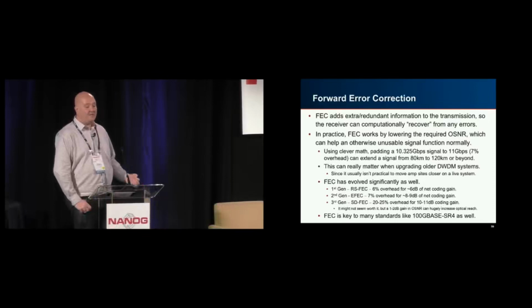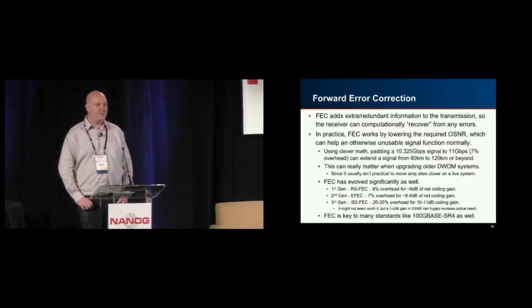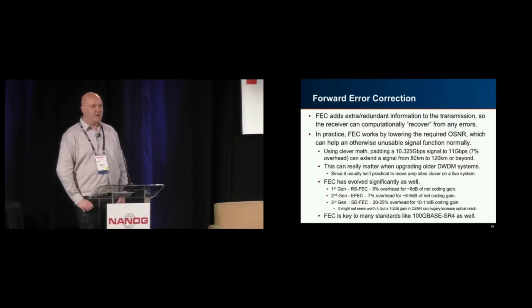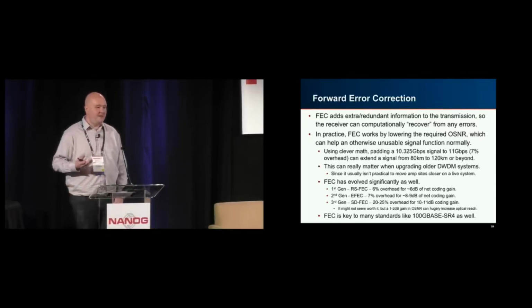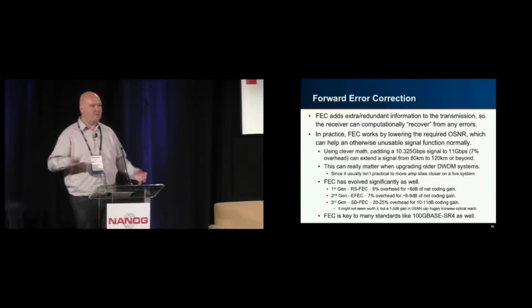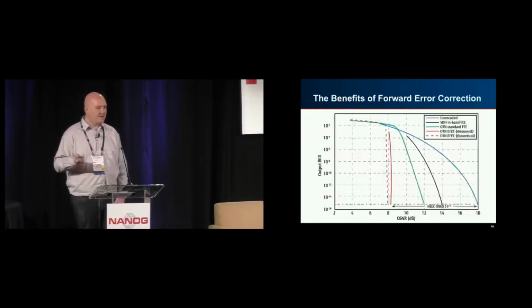That can actually be huge. That can make the difference between a system working or not working. That can make the difference between a system that can do 100 gig per channel or one that can do 200 gig per channel, quite easily. So it's worth it to put all that extra data in. And you see FEC has actually become very critical to even commodity pluggable components as well. Things like 100 gig SR4 technology pretty much require FEC to work, even though you're only going a few meters over a local patch cable. You've got that built in, and you'll see that more and more. Most systems have to have FEC built in just to work with these commodity optics.